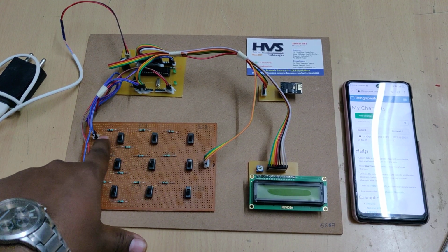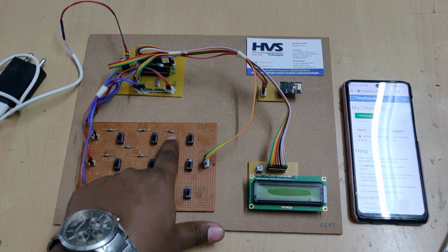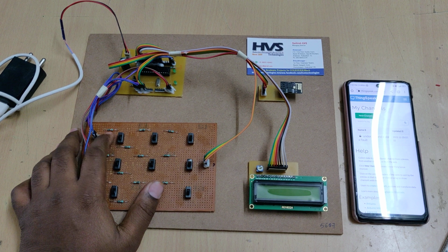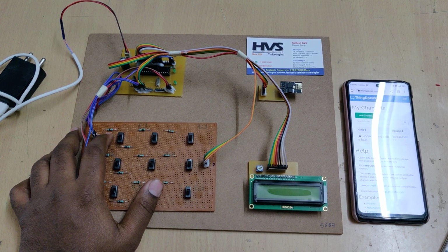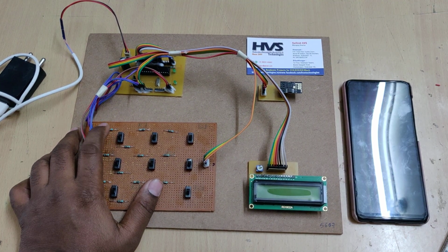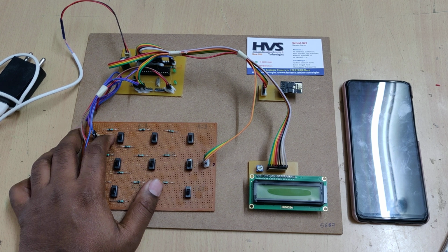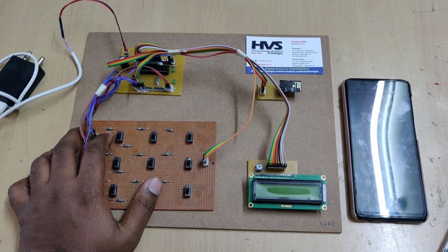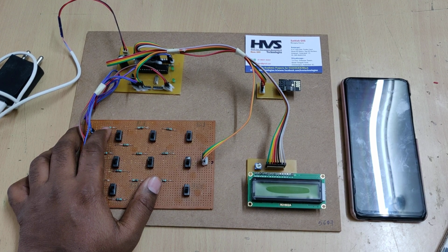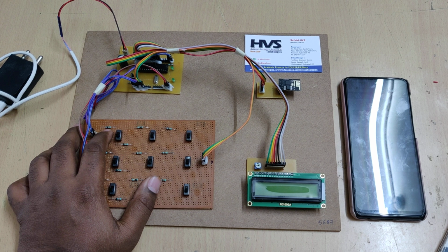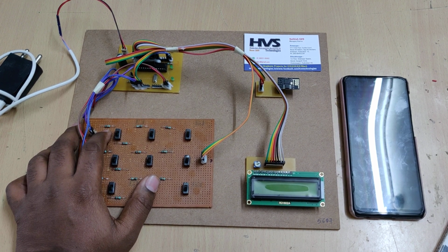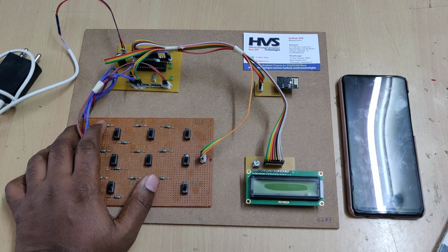For 10 kilometers, that means 1 kilometer, 2 kilometers, 3 kilometers. So a 10 kilo ohm resistor is placed at each kilometer of distance. Whenever a short circuit happens, the voltage drops in parallel. Based on the wire length, the resistance varies. Here, 1 kilometer of wire length is assumed to provide 10 kilo ohm resistance. That means 1 kilometer of wire will provide us 10 kilo ohm resistance.